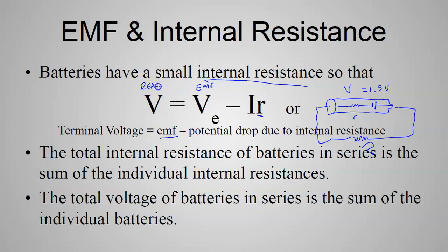voltage. So maybe my battery is 1.5 volts, and I touch it with a voltmeter and it says 1.5 volts. But then I put it to a battery test, or I run it through a resistor, close the circuit with it. Current starts to flow. There's going to immediately be a little drop there, a couple tenths of a volt typically. Until the battery goes bad, and that's part of why the battery would go bad. Okay, that's something to think about.